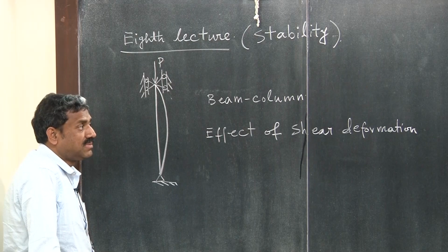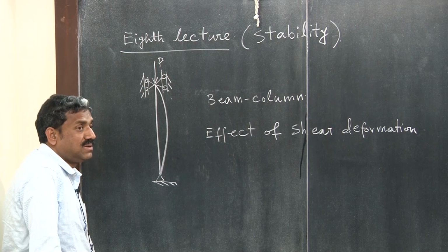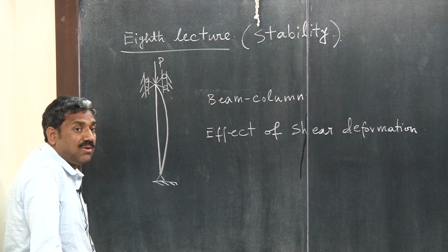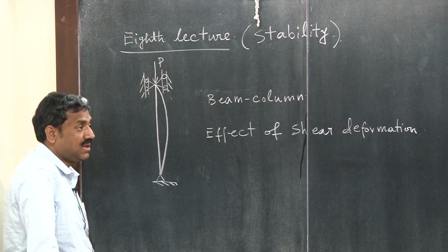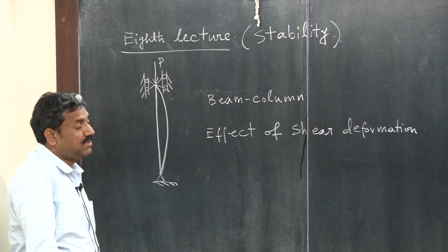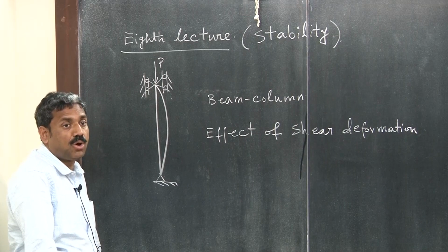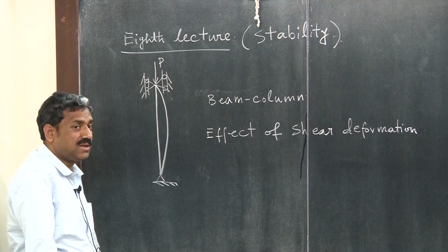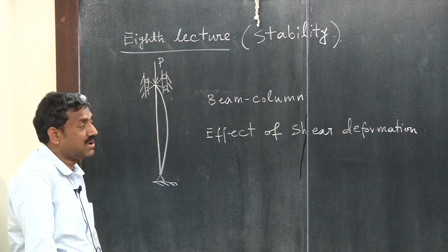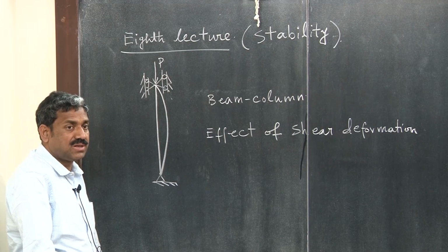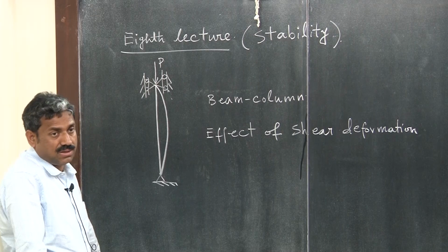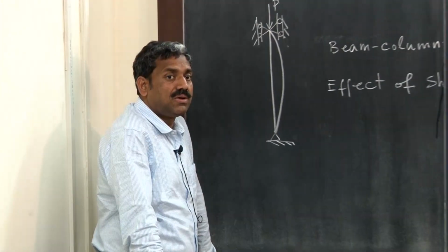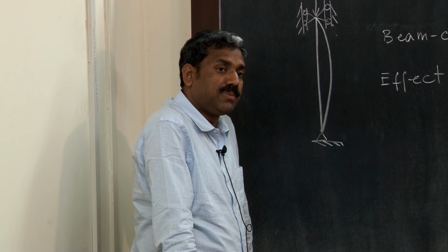Of course, shear deformation is significant, as you all know, in beams, plates and shells when the span by depth ratio is smaller, right? Generally, if it is less than 10 or less than 8, then we consider the shear deformation to be significant. We have learned Euler-Bernoulli beam bending theory. But if you include shear deformation, that gives rise to Timoshenko beam theory, right?